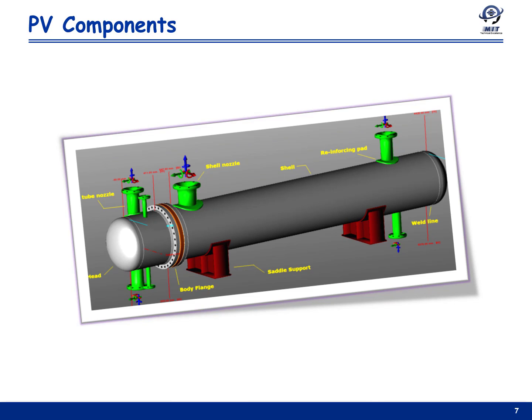Generally, pressure vessel components are categorized as pressurized and non-pressurized parts. Pressure components include shell, heads, or nozzles. Non-pressure components include supports, which can be saddle type, skirt, legs or a lug, external attachments, pipe support clips, ladder clips, etc., and internals such as vortex breakers, tray support ring, etc. Although these internals are inside the vessel, in most cases they are not the main pressure containment parts.